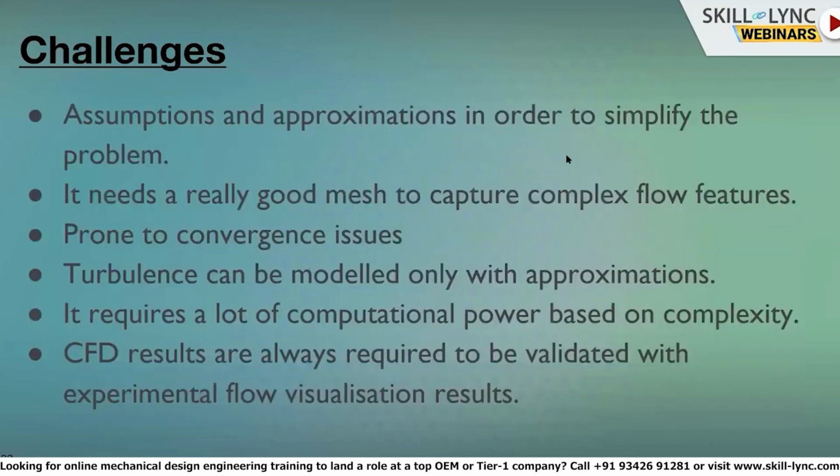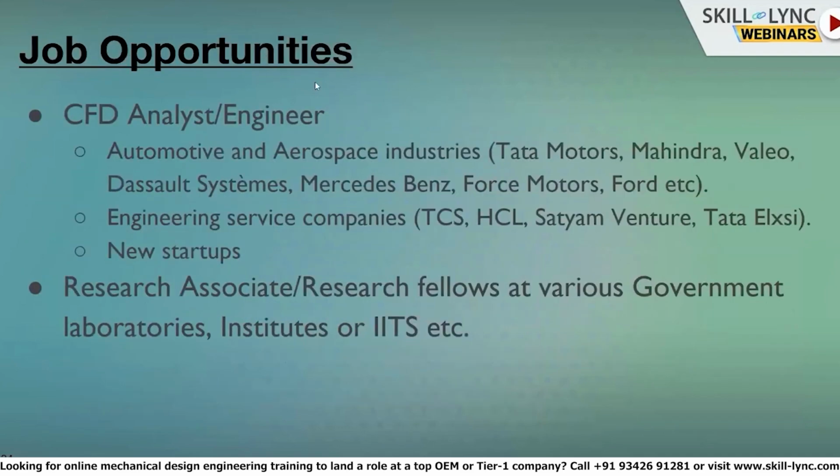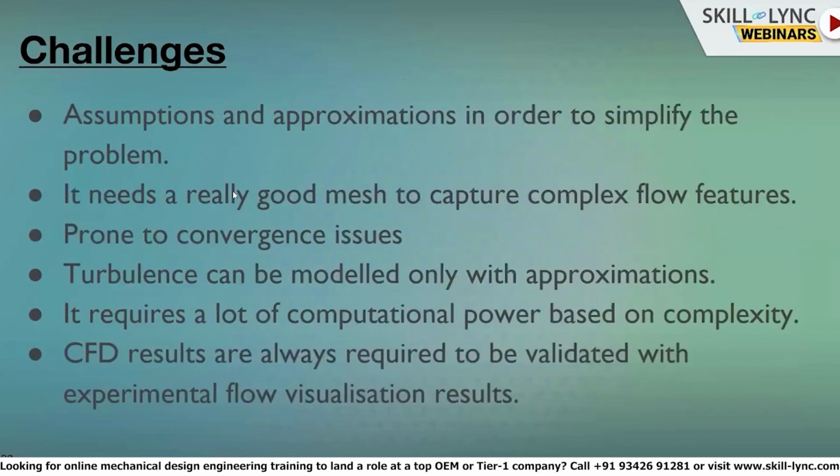Yeah, and challenges. I have already mentioned in some of the slides the challenges for a CFD process and CFD engineer, so I will repeat it. We always make assumptions and approximations in order to simplify the problem. That is the biggest challenge for us, because we need to know how much we have to assume and how much we have to approximate. That is a judgment based on your problem, your experience, and the type of results you want. So that is always a challenge.